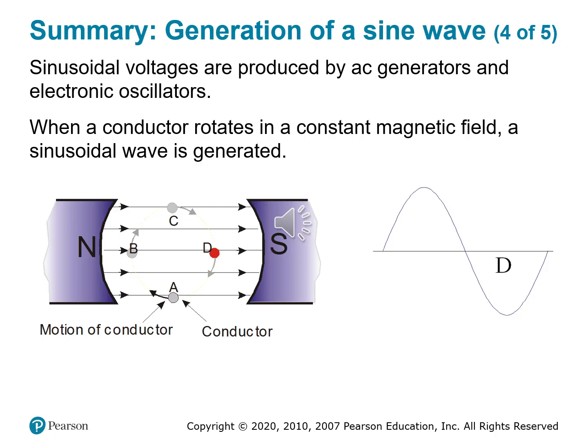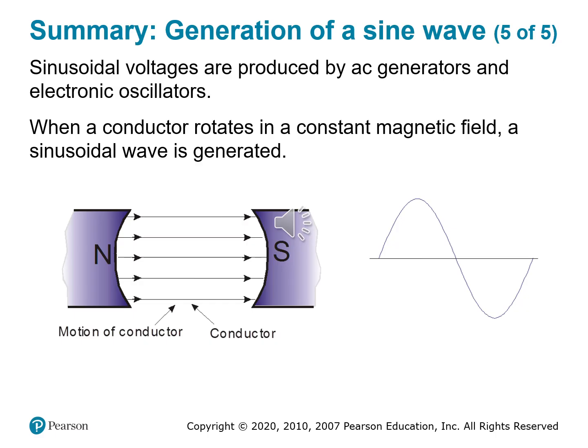So maximum field interaction occurs here. You have full polarity reversal and the symmetry that defines sinusoidal AC. So it's motion turned into electricity, and motion turned around to reverse electricity, just by rotating a wire in a field. So we end up back where we began, one full complete cycle.